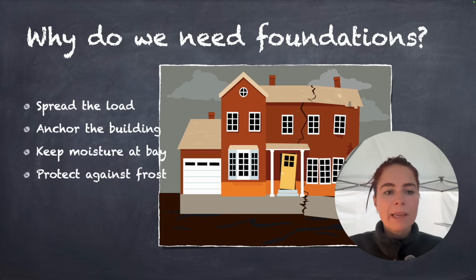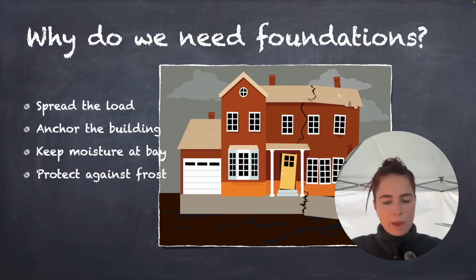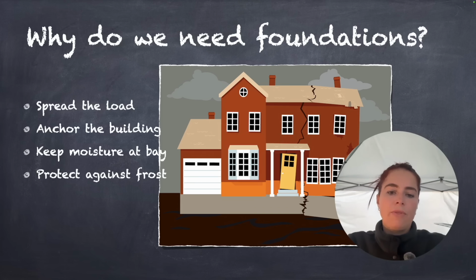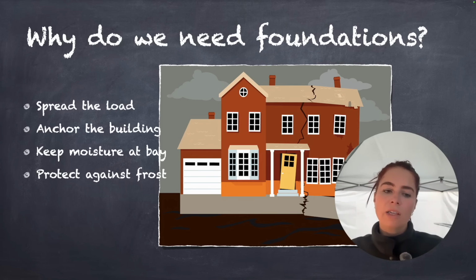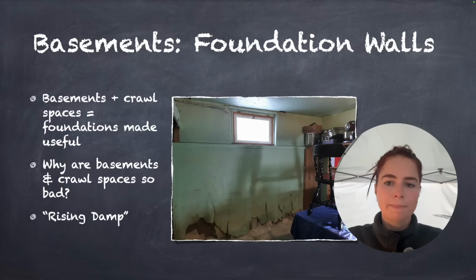And finally, it protects against frost. Because the water in the soil freezes and it does expand. And if a foundation is not below that frost depth, this freezing soil can cause frost heave. It'll pull upwards unevenly, and it can cause cracking of the walls, sticking of windows, sticking of doors. So for those reasons, we need a solid foundation.